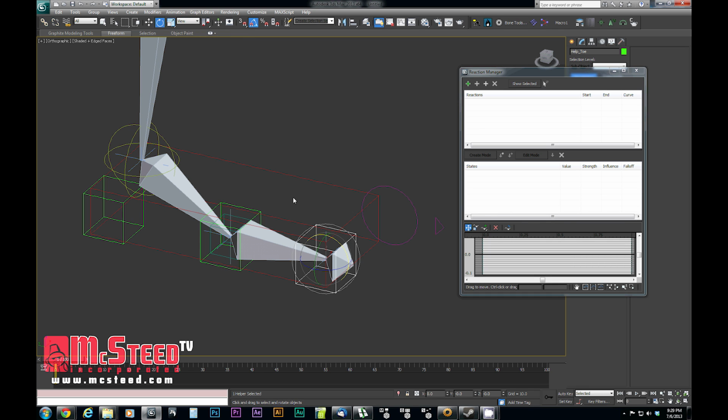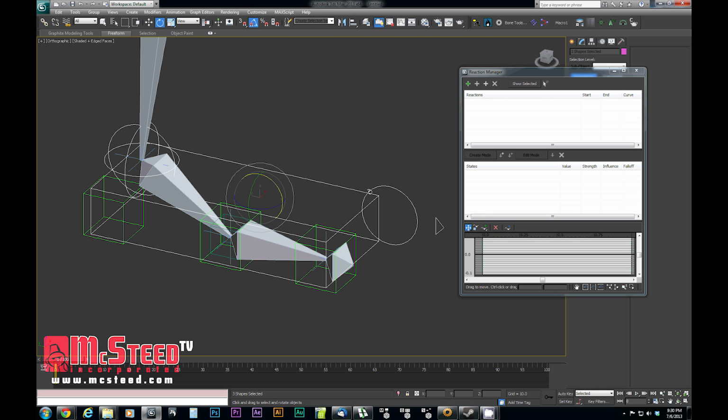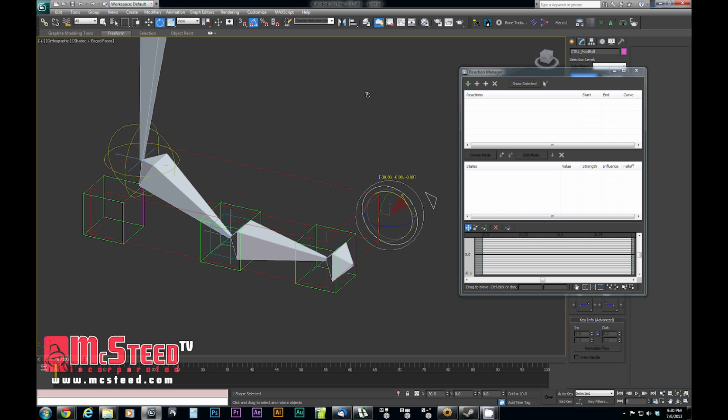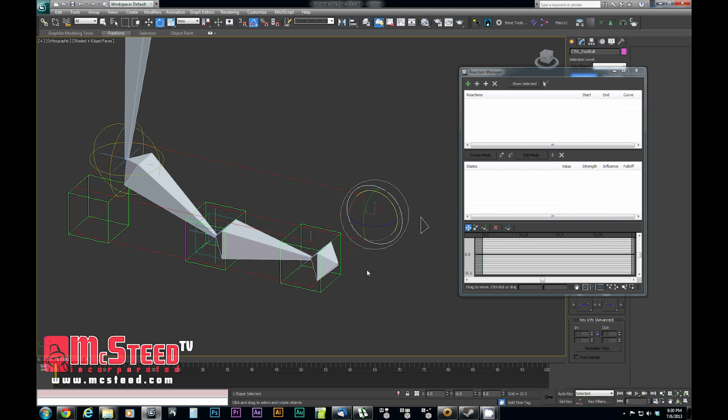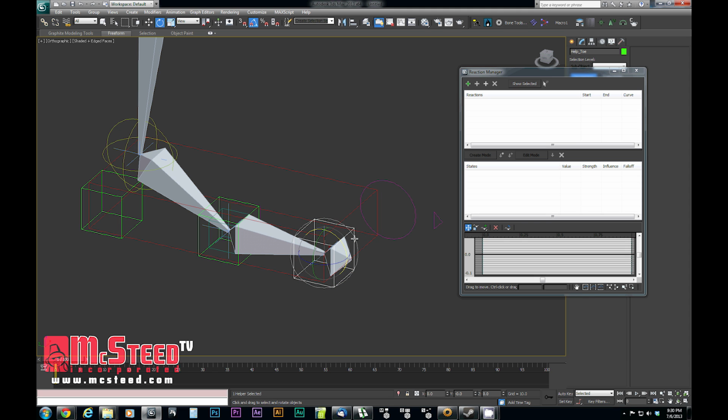And what we need to do before we set up any of these reactions is I'm going to select all three of these controls. I'm going to freeze their transforms. And what this does is it gives you the ability to not only zero out the rotations or position. See, if I rotate this, I can always go to Alt right click, rotation to 0, and it'll always snap back. But in addition to that, it gives me a 0 starting position for the driving of these other objects. Because if there's already rotation on there, it's going to add rotation to the objects that are being driven.